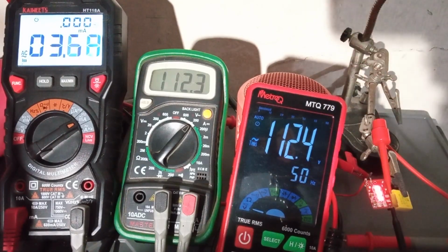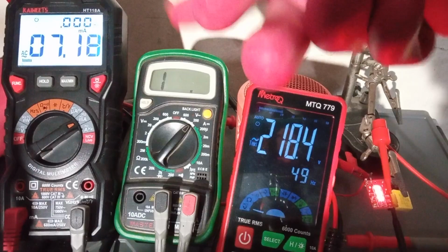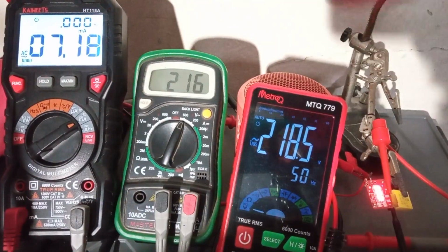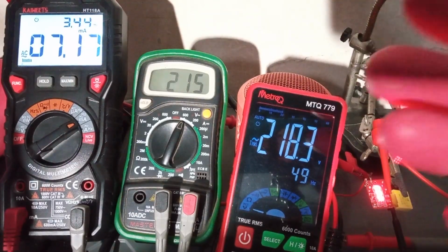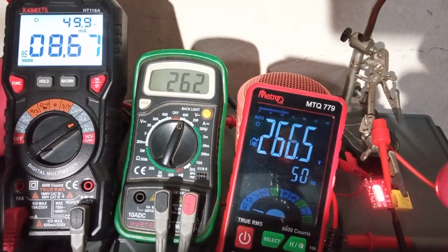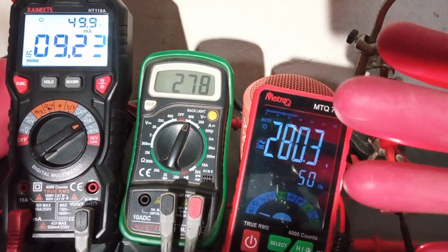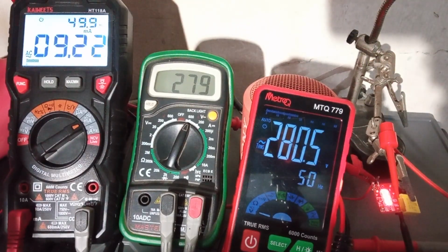So if I increase that to, let's say, 210, something like that, we are around 220. And the voltage across the capacitive dropper is actually over limit, so I set it to 600. And it shows that we are dropping around 215, 216 volts, which makes sense. So if I keep on going at around 300 volts, this capacitor is rated for max 310 volts AC. So we are around 280 volts, and we are dropping around 278 or something like that.